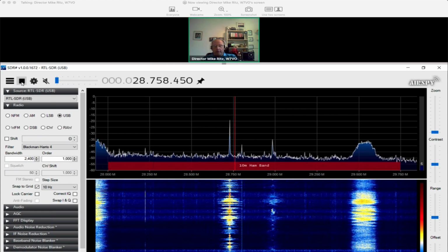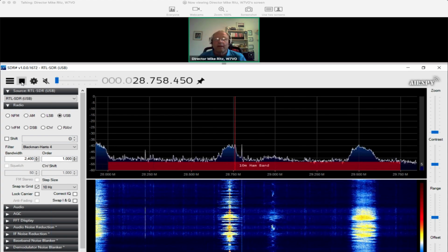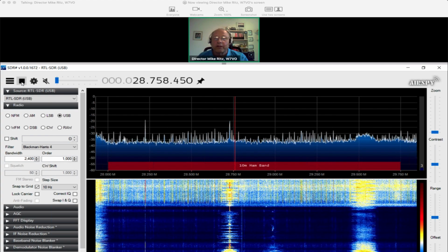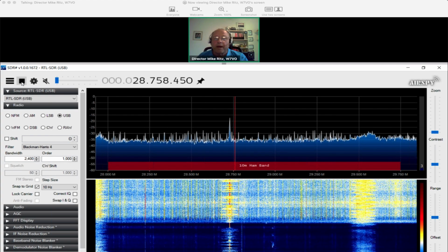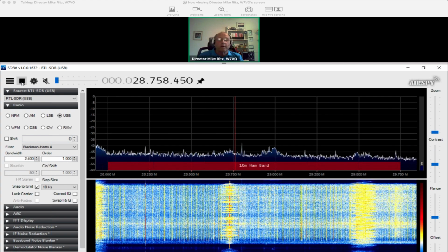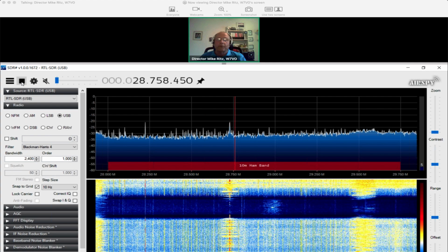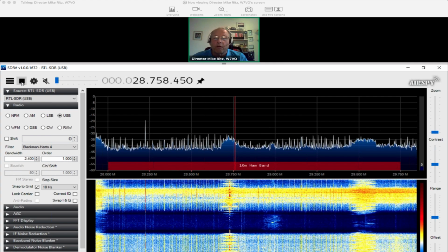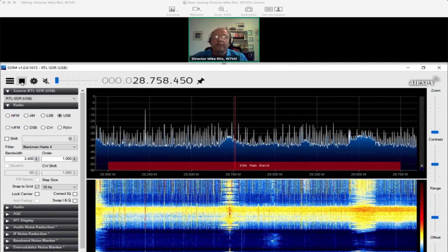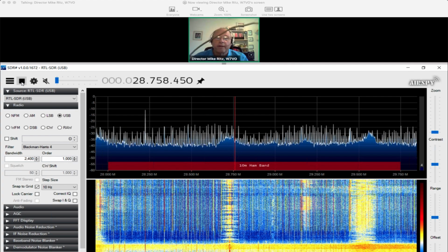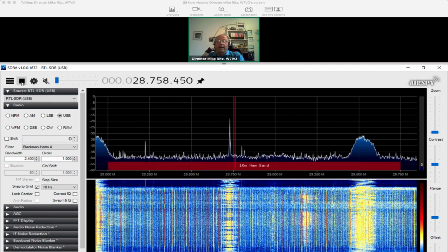And I'm going to put this thing right next to my laptop. And what do you see on the screen, right? You see all the noise, and look at all those little noise spikes, and look how high the noise floor goes up. It goes up by probably 20 dB when I get close to my laptop. If I go next to the laptop screen, now I've got the antenna very close to the screen, and look at all that noise, right? So this is just a little simple loop antenna.